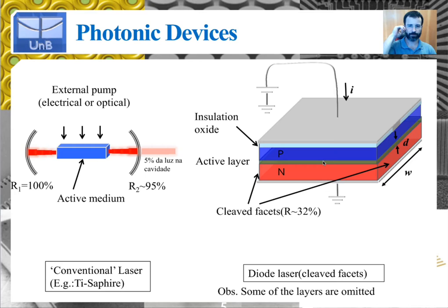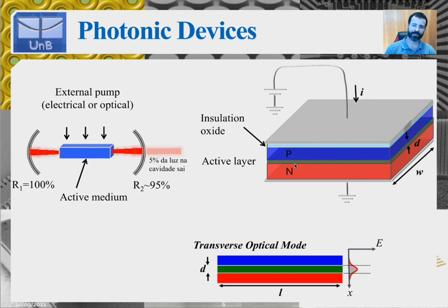And through stimulated emission, which is started by spontaneous emission, light will be generated, and the lateral facets of this rectangular chip here will be poor mirrors, but mirrors nonetheless, which will reflect light. So you can imagine that the light will be reflected on this left and right facet here, back and forth, because usually the active region will form an optical waveguide that will support a transverse mode, such as illustrated here, and this mode will be able to propagate back and forth, be reflected at this facet, and then propagate back and be reflected at this facet back again. And so the generated light will go through the gain medium several times and be amplified, and light will come out of the laser. So this is just an illustration of one way that lasing could be achieved.